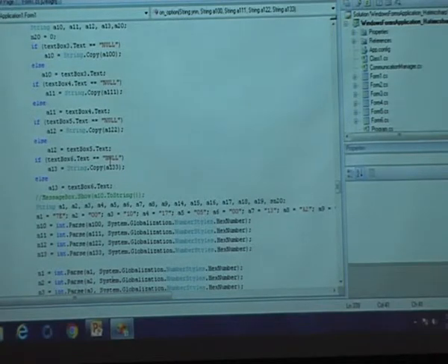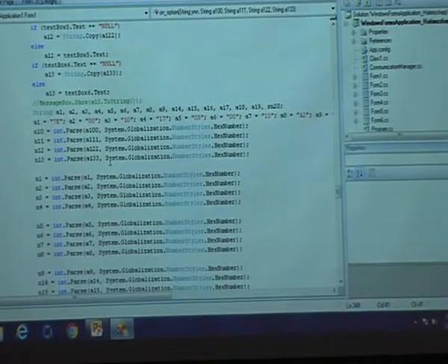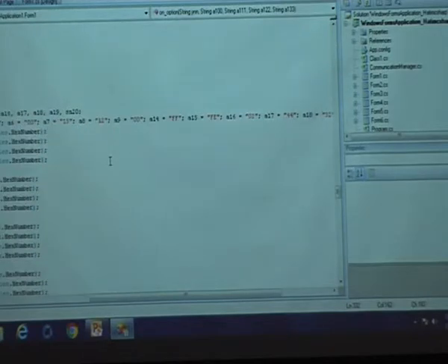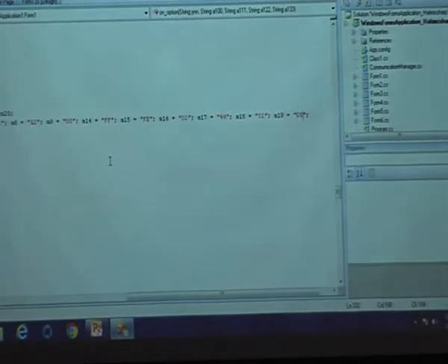It means you need to write that frame's values to the serial port so that the coordinator sends those values to the corresponding remote ZigBee. That's the logic of this particular program. So get those values. This is the complete frame here. 7e 0010 0013 A200 is the higher order address bits, followed by 0013 A2 00, then FF followed by 02, 44, 32, and finally you are making that value 5. 5 means making the value on.